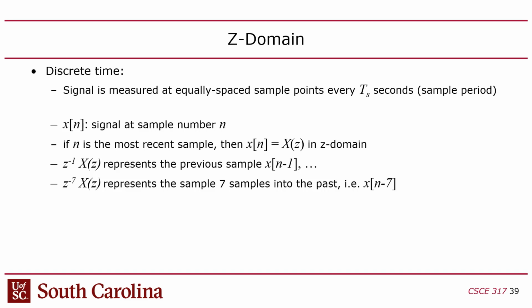What if I want to build a computer that does that control? It can't be done. You can't design an S-domain controller. It's impossible. That's continuous. Computers are discrete. So there's a big problem there. So what do you do? Well, there's a few ways to deal with that. One way to do it is using the Z-domain instead of the S-domain. The Z-domain is the equivalent of the S-domain, but for a discrete controller.